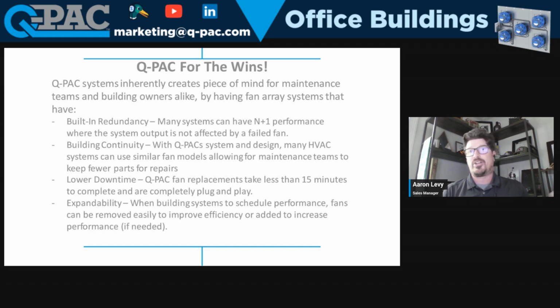If there's a building with any significant amount of air conditioning in their system with belt drive systems, I guarantee there's a maintenance shop somewhere in that facility with a wall of belts on it, like you saw in the picture a few slides ago. It just makes their lives easier to say, I have 2 fan models that'll contain my entire building, and this fan goes through these 30 air handlers, and this fan goes to this 5. So they have fewer parts to keep on hand.